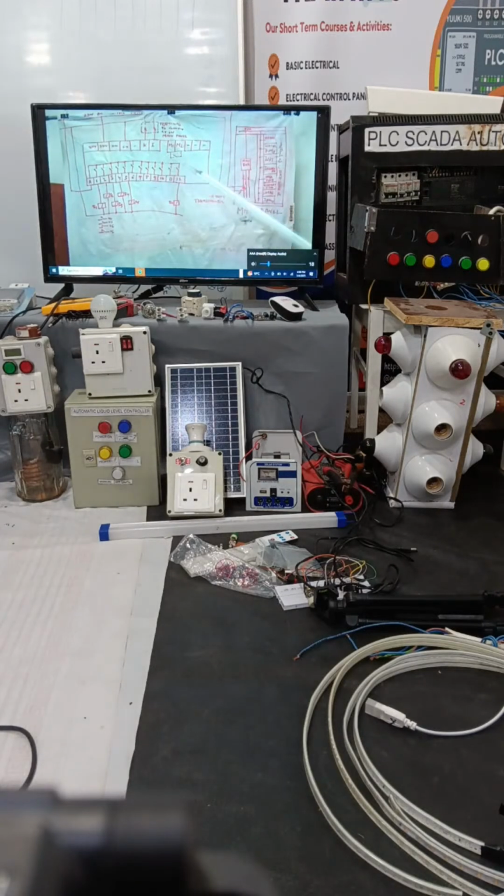This will feed to this point K and I. So this is a comparator. Inside we have to put the target power factor, 0.98 or 0.97 or 0.96. The comparator will compare the power factor of the system, and it will give a signal to close these contacts 1 to 12. Depending upon how many kVA are required, these contacts are closed or open.